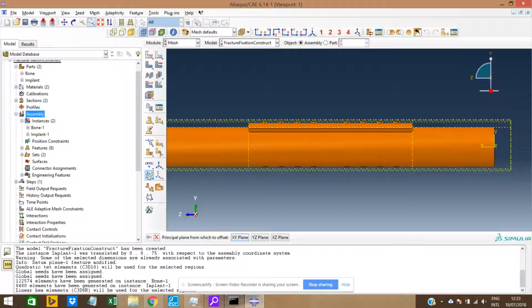Then I'm gonna make some more planes, but I'm gonna make them with reference to this one. So for example, this one, it's gonna be like that. You have to define whether you want that in direction or flipped. So flipped and 15, and that's directly in the middle of this screw. Then another one, flip, 15, then another one, probably flipped. Oh no, I didn't flip. So 15, another one. I'm doing this like this because I'm constantly using 15, so it's easier.